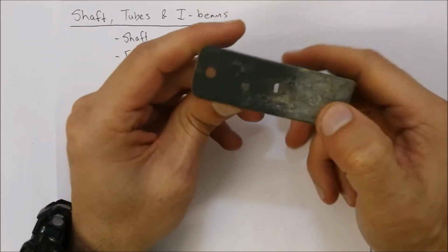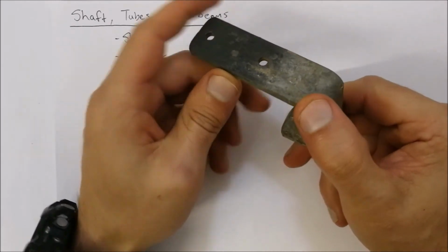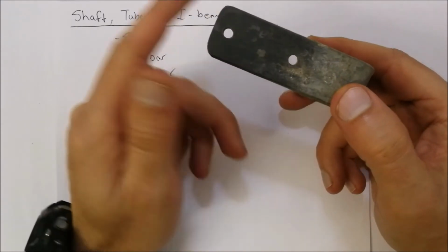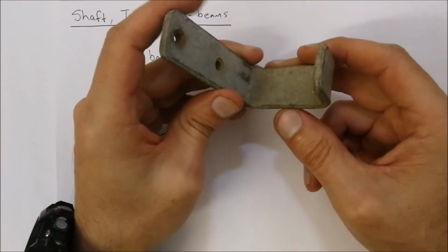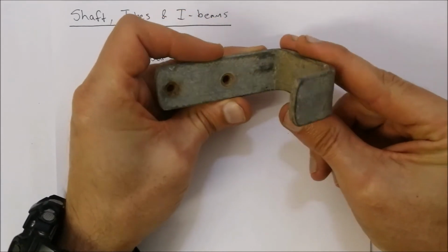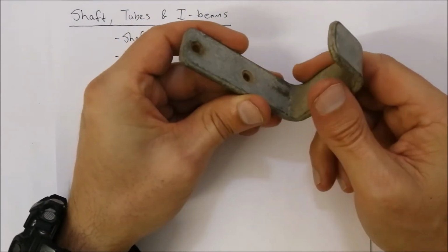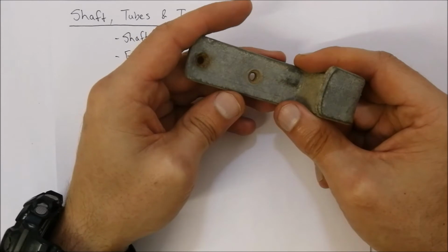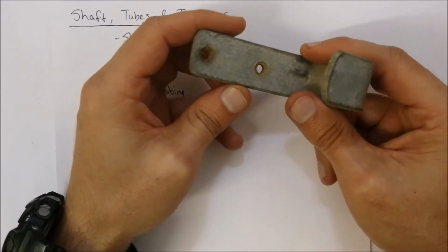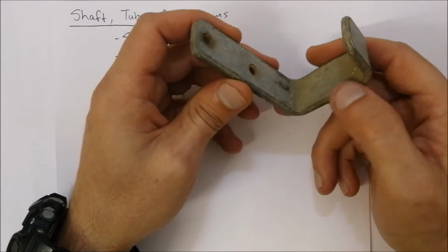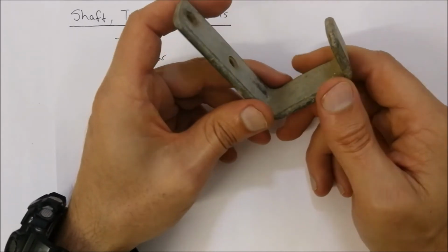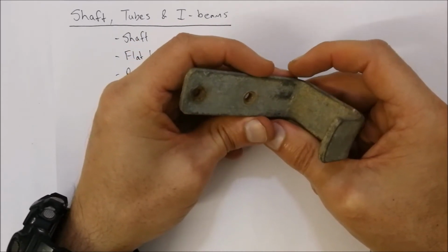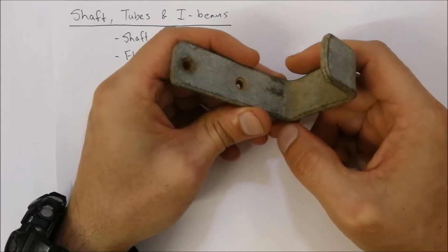You will notice if I turn this flat bar around this side, I clean it up over here, essentially it is mild steel, but this specific piece has been galvanized. So it's a zinc layer that has been plated on top of it. You get different ways that you can get the zinc layers on. You can have a cold spray that you spray on, but usually it's a hot dipping system or electroplating system that happens. So essentially with zinc it is also less prone to corrosion,